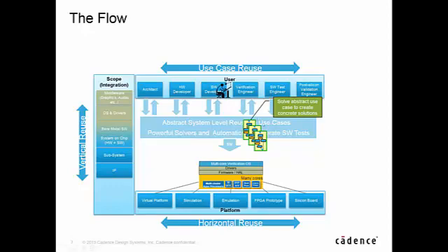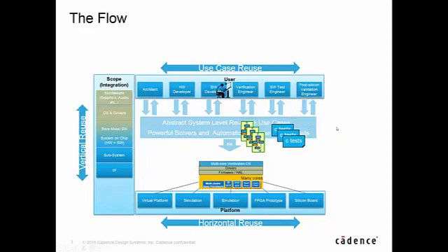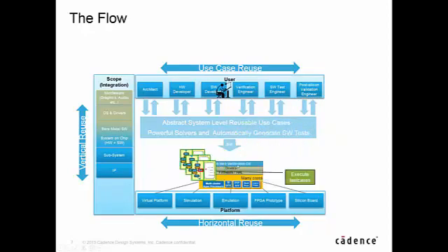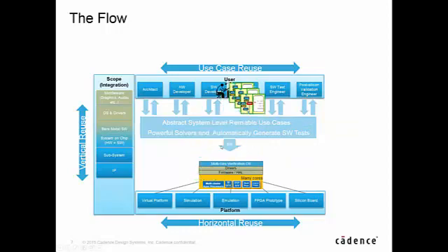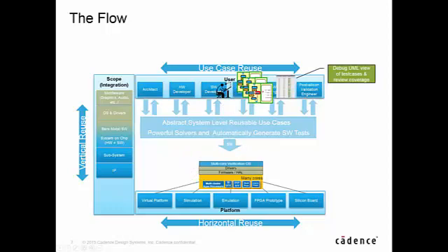So those concrete solutions can in turn be generated into C tests. The C tests can be executed on the different platforms, and then the results of those C tests can be used in that same abstract form for debug and analysis. So you can look at your coverage, you can look at the actual execution that occurred of the test and go in and debug it at the abstract diagram level or down into the detailed C software debug kind of level.